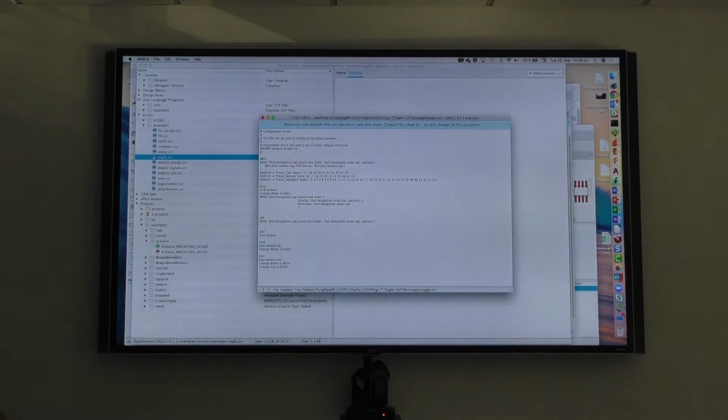When are those commands executed? When you first start a new design? Yes. When I start a new design, when I start a new library, if I go into the package editor, if I go into a new schematic, yes. If I start a new schematic, all the grid settings are as defined there.